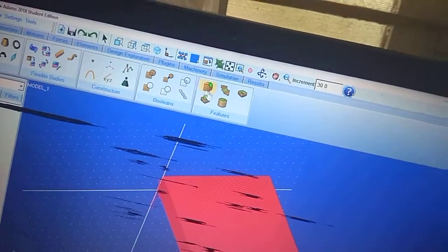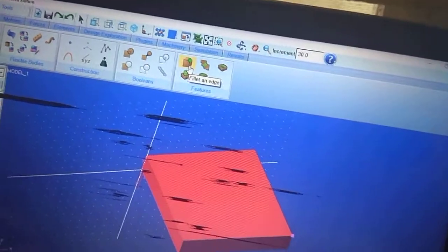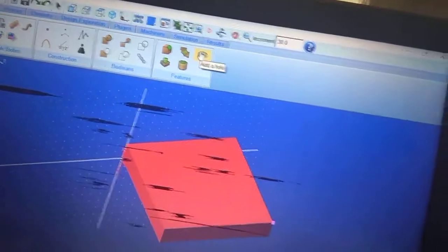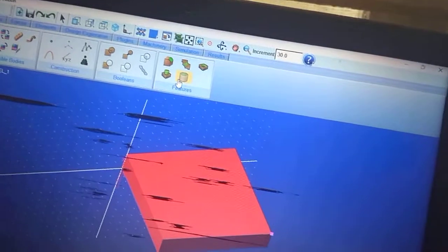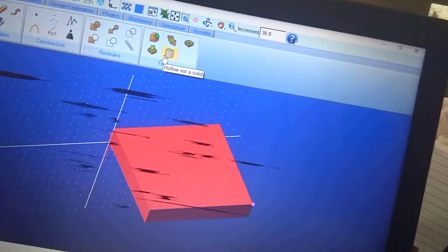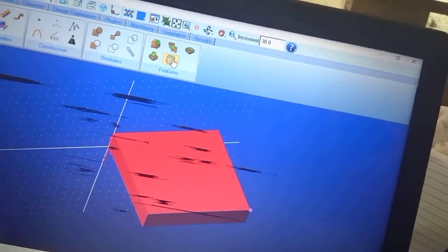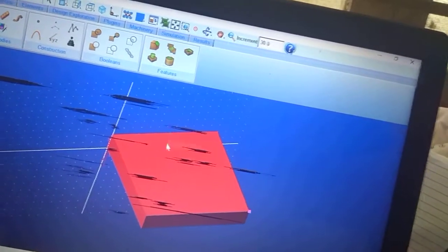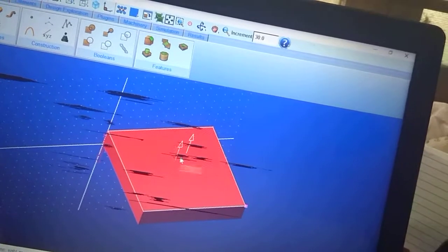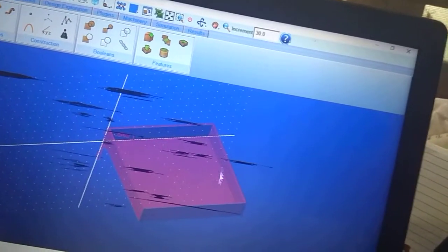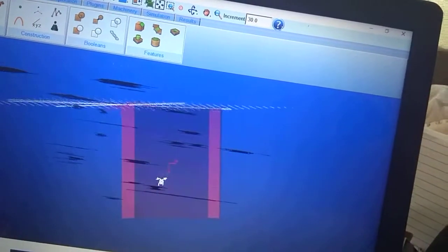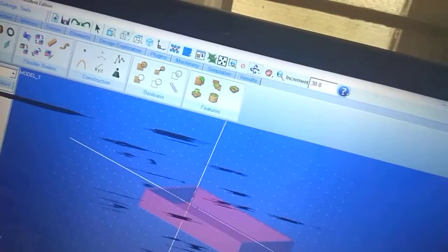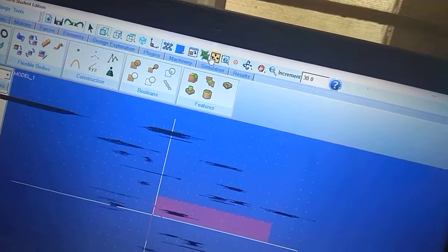Now if you know SolidWorks, you'll also know these. This is the fillet. Through this you can actually make small holes. Through this you can make extrusions and emboss. Through this you can make an object into a solid shell, a hollow shell. For example, let's try this shell part. You have to click on the shell, choose the object, choose the face, and right click. It forms a shell. It's like a little box. It has a base to it. So you get it. So let's go to front view. Okay, so that's about moving the object.